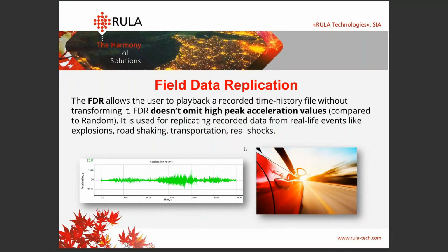The idea of field data replication is that you replay the previously recorded time domain data on your shaker. If the actual conditions of operation of your device under test are at hand, it makes sense to record those with the recording option of desktop in your lab or a portable recorder or in a different way, and then simply reproduce it on a shaker. It would make sense to compare the FDR results to the results of testing your device under test with regular mathematical modules like random test.